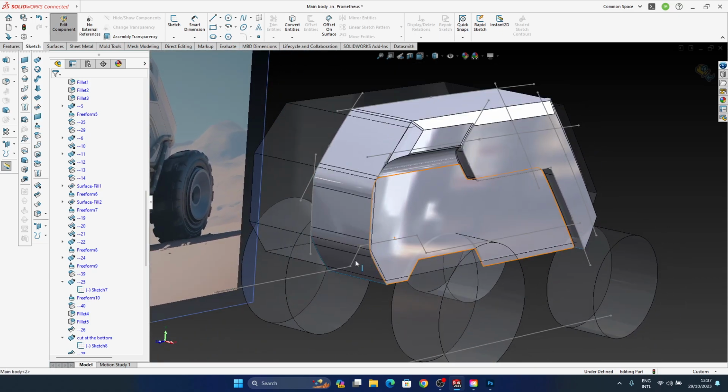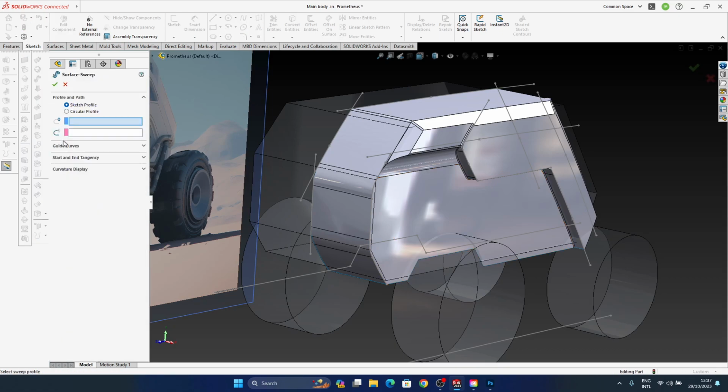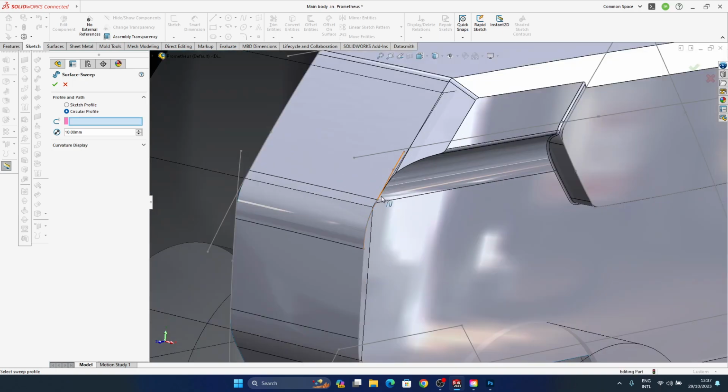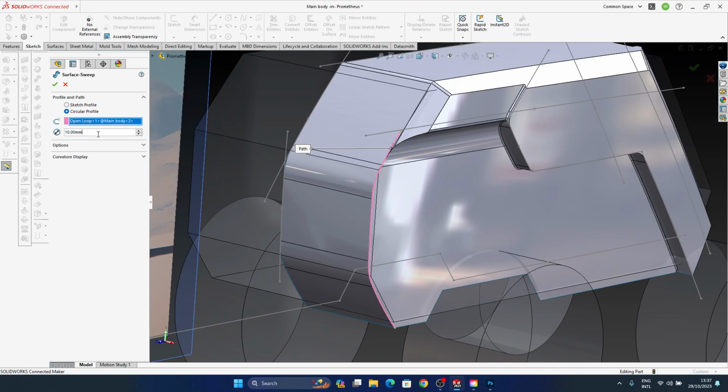All right. So now, if I remember correctly, if I do a sweep surface and select circular profile and select the curve, let me select the whole curve there. Come on, that's it, good. And if I select 100, is it a diameter in there? I think I have a diameter, so 300 millimeters for a diameter.